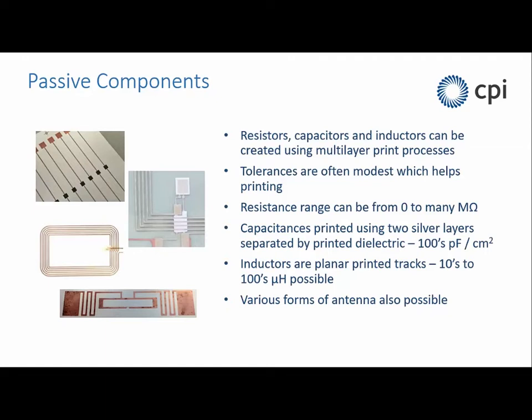The capacitors that you see there in the center, little parallel plate capacitors, can be used to produce hundreds of picofarads or even up to nano or tens of nanofarads if you need them. We can't get up to microfarads, not with conventional capacitors, although a combination of the supercapacitor technologies with conventional printing processes should mean that soon we will be able to get up to microfarads or hundreds of microfarads quite easily on these little printed forms.